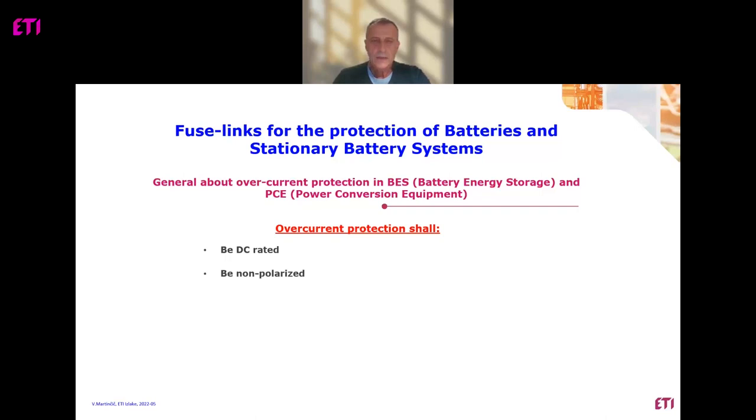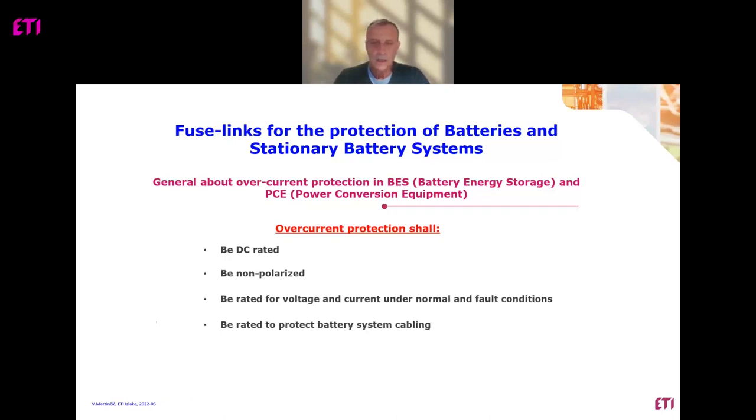Then it shall be non-polarized. Rated voltage of this system and rated current should be defined under normal and fault conditions. Overcurrent protection should be rated to protect battery system cabling, so connection cables should also be protected. Meet relevant product standards.